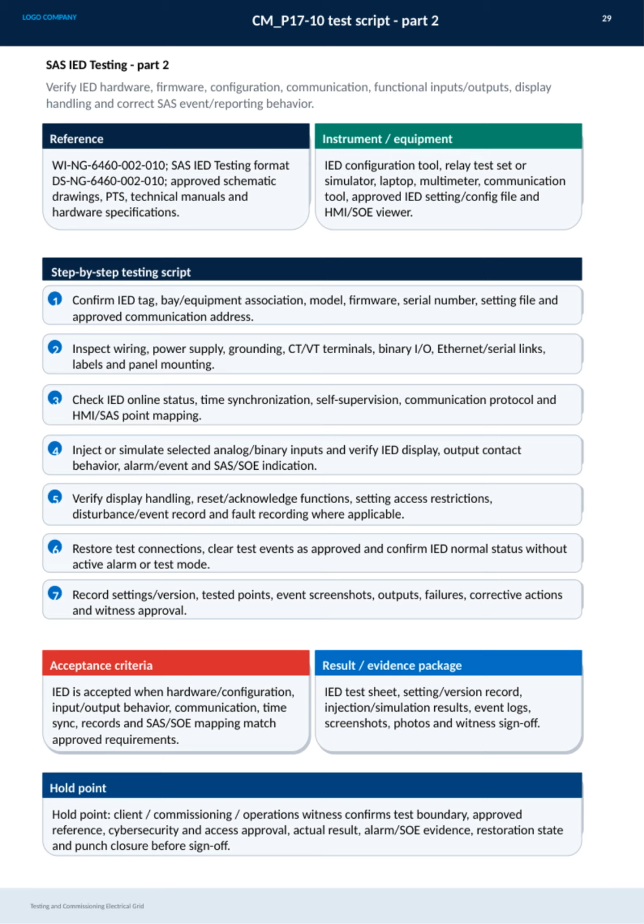After testing, all connections are restored, test events cleared, and the device's normal status confirmed without any active alarms. Throughout this process, detailed records must be kept, including settings, test points, screenshots, failures, corrective actions, and witness approvals. The IED is accepted only when hardware, configuration, communication, time sync, and mapping fully comply with approved requirements.